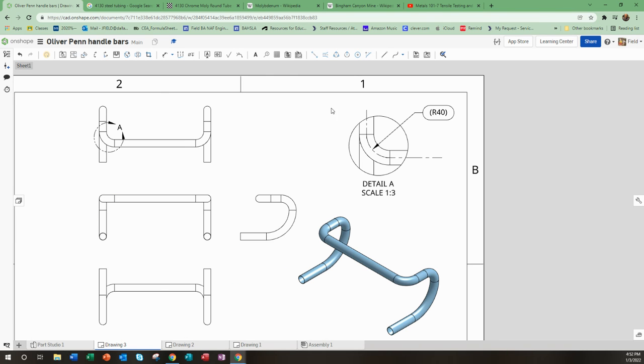Again, let me show you another quick example, and I'll ask you guys to add these centerline sketch elements here, because it might be really important for the viewer of the drawing to know that, right? How many millimeters total distance between those two bends? What else might be another really important dimension to know, right? You need to know all these radiuses, so we could get in there and do that. In fact, I might ask you to go ahead and do that here.